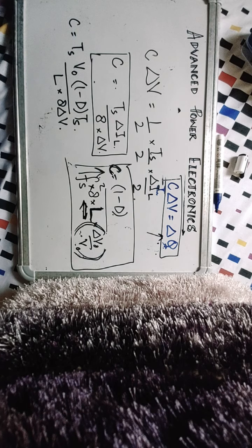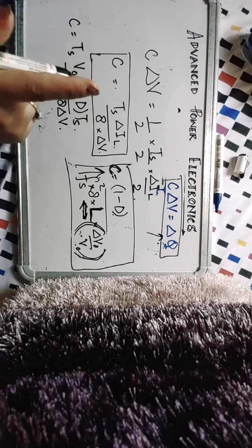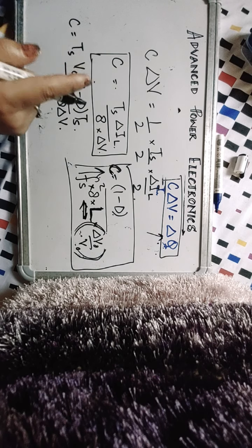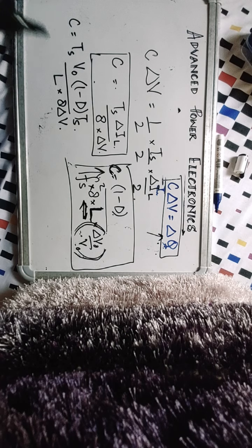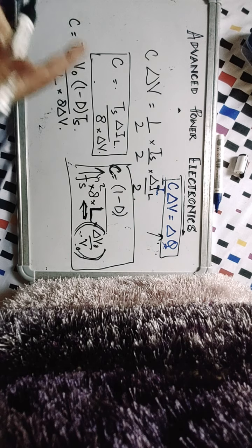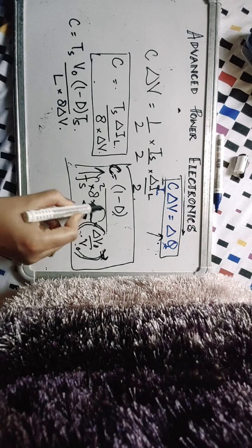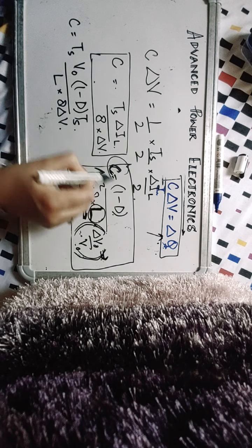Now when the capacitor current has less ripple, and the capacitor current's ripple determines your capacitor voltage's charging and discharging, so obviously your capacitor voltage will have less ripple, and that is your load voltage. So the ripple in load voltage is indirectly affected by L also and not just by C.